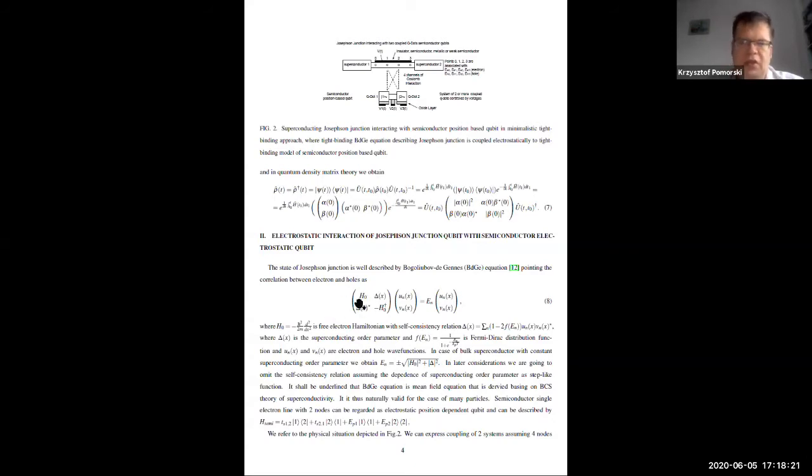There's also an assumption in those equations that there is a kind of symmetry between electrons and holes, that electrons and holes have the same effective mass, and basically the hole represents an anti-electron, or conversely, the electron represents an anti-hole.